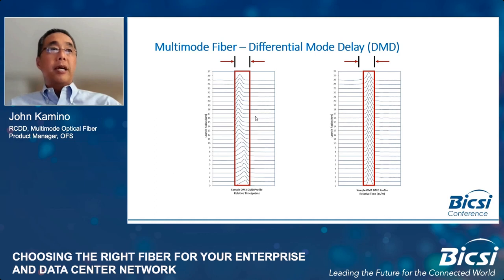You can see when looking at the OM3 fiber on the left that light traveling at the center of the core at radius 0 arrives slightly earlier than light traveling nearer the core clad interface. And thus you have a wider pulse width. On an OM4 fiber though, if you look at the fiber on the right, you can see that all the way from 0 out to 25 microns, that pulse, regardless of what path it takes, arrives at nearly the same time.